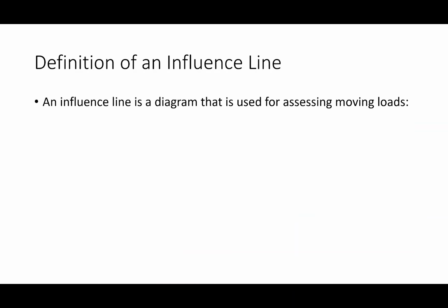So, let's talk about an influence line. What is an influence line? An influence line is a diagram that we use as structural engineers for assessing moving loads. So we have a structure, the loads move, how do we deal with that? We use an influence line.